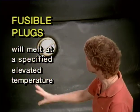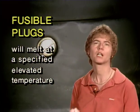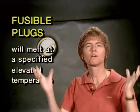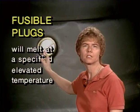In other words, when that whole tire assembly has gotten really, really hot, rather than the tire blowing up, the fusible plug will melt and it will release the tire pressure. But what that means is that that tire has really been abused. The tire should be scrapped, just thrown away, if it's been subjected to a temperature high enough to melt one of the fusible plugs. If it's melted the fusible plug, it's had enough heat, enough abuse that you need to just simply get rid of it.